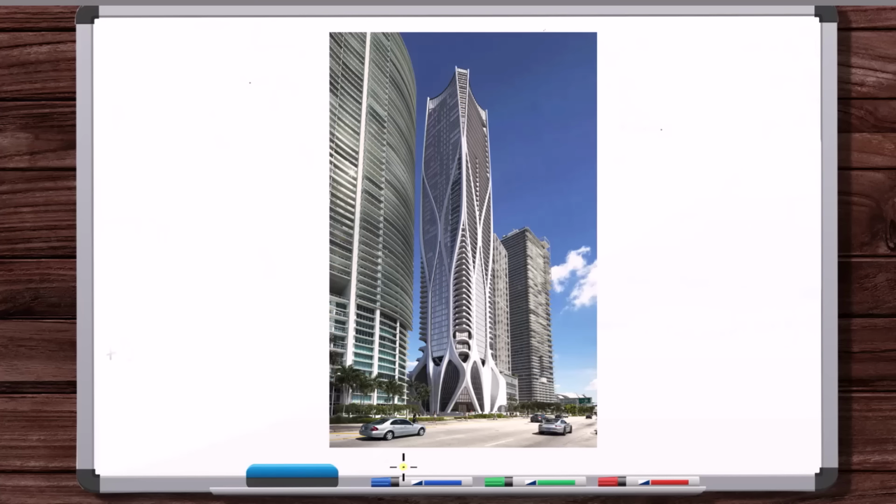Let's come back to the skyscraper example. So again, for any load analysis or structural analysis of some system, you want to think about the skeleton. The skeleton is where all of the main loads are traveling through. So in other words, this looks to be aesthetic. All this white here, it kind of looks like that's load bearing, but to me, it's probably only bearing the load of the weight of what's on top of it here, of the aesthetic piece. This is not part of the skeleton.